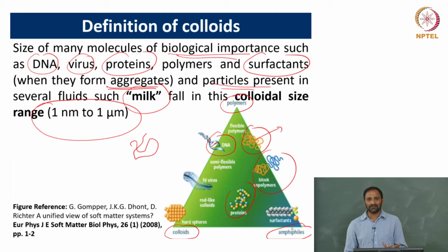But you could have a system where two polymers are connected by a covalent bond, as in the example given here. The orangish color is one type of polymer, and the blue is another type of polymer, connected by a covalent bond. That is an example of a block polymer. You have two different polymer molecules joined together, which is why it is called a di-block polymer. You can have 3 different chains, called a tri-block polymer, and so on and so forth.